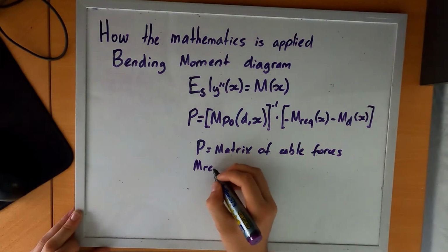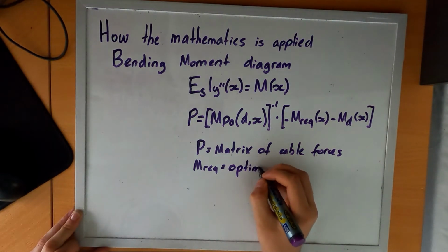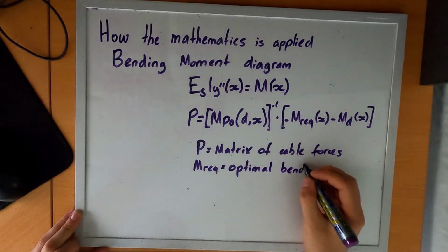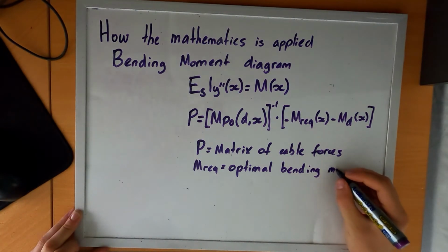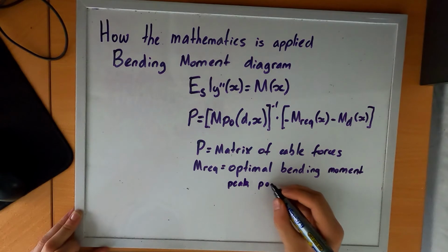These formulas allow for the dead load bending moment diagram to be drawn up. This diagram, along with the live load bending moment diagram and the vertical reactions of the elastic supports, are used to draw the resulting bending moment diagram for the structure.